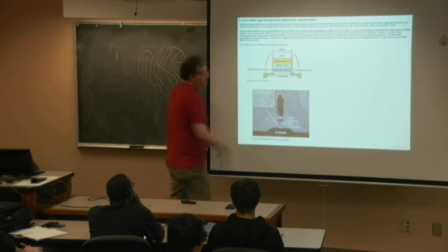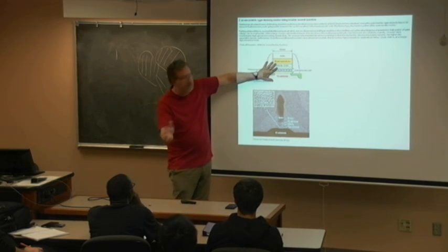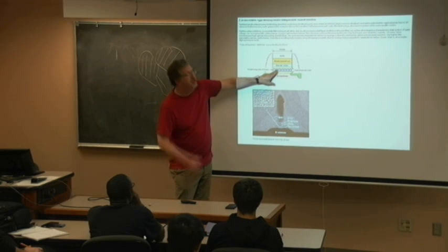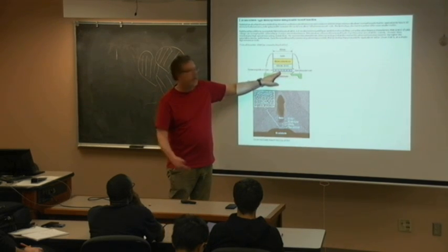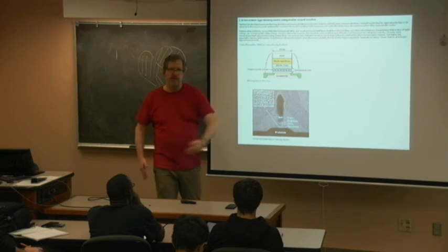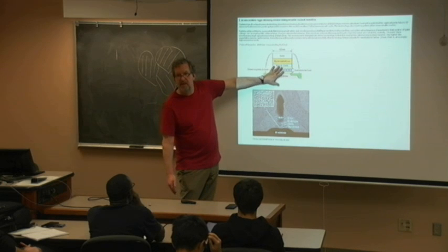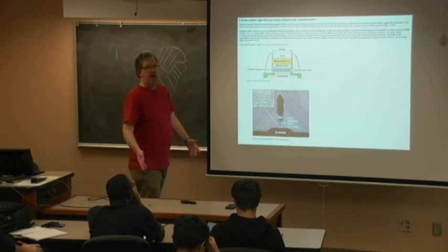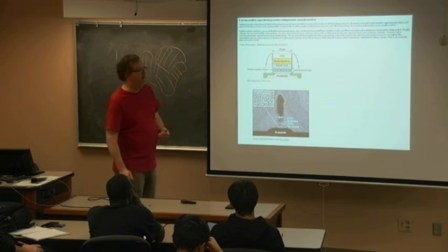Later we'll see how the threshold voltage of a transistor works. I haven't taught you that yet. But this will shift that threshold voltage, so I can essentially program this. I can turn this transistor so it will represent a 1 or a 0. And I have to have millions and billions of these to represent my latest cat video on my USB stick, right?